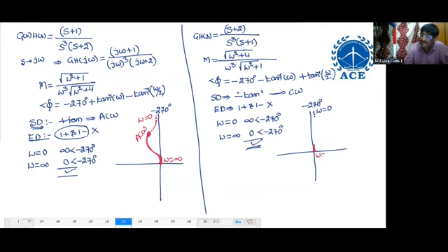Omega infinity. This is the plot. Don't draw like this. It is not touching the what? Minus 360, touching minus 270 only. Look here at the ending angle. Clearly observe the plot at omega infinity. It is moving only towards minus 270.